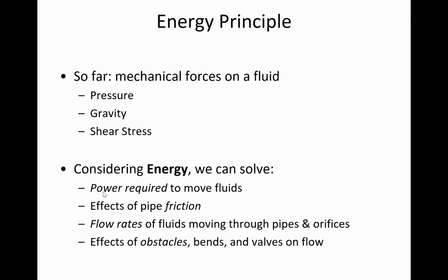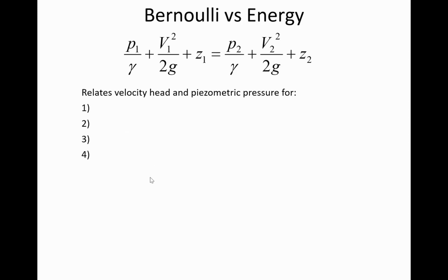And so the energy equation, when I show it to you, is going to look kind of familiar because it has many of the same terms that Bernoulli's equation did. And so here on the screen is Bernoulli's equation, and what it relates is the velocity head and the piezometric pressure. And what we said with Bernoulli's equation is that when water is flowing through a pipe or a nozzle or from one place to another, that energy just changes form.